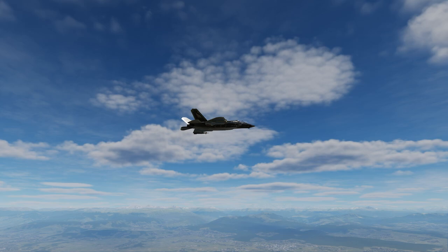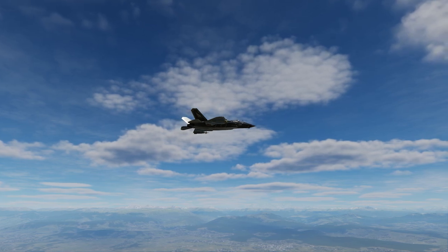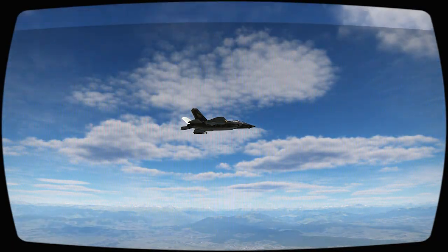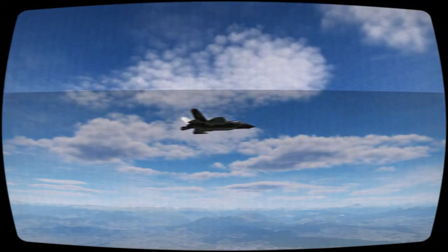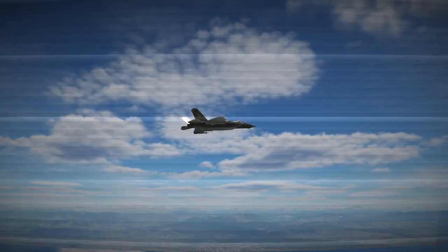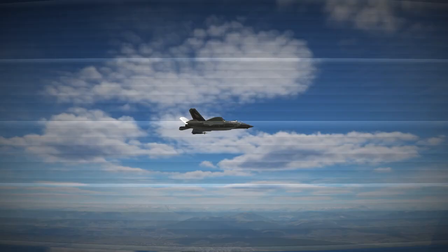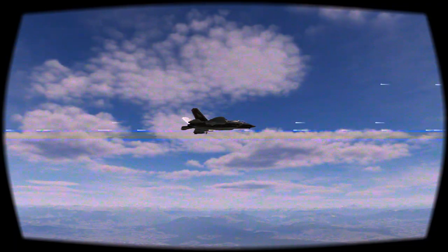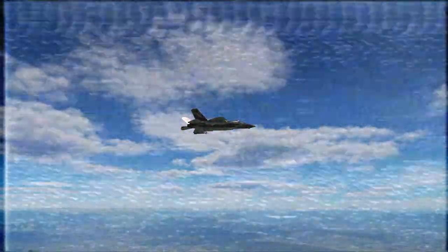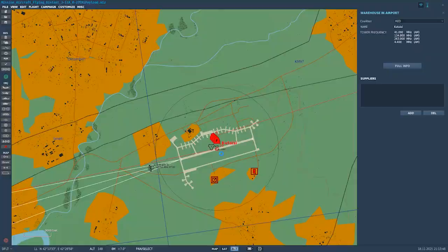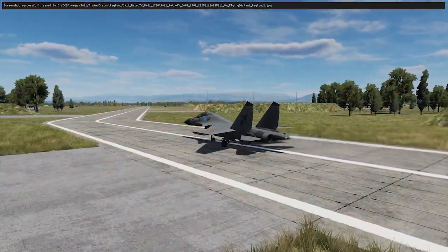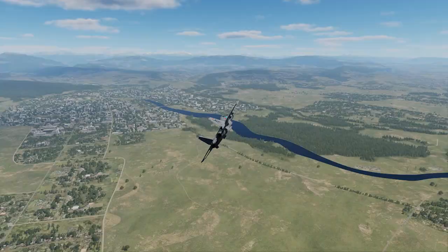Given that images in the computer are created without natural camera artifacts, we utilize tools such as Reshade to apply image filters on our captured images to help simulate real-world camera response and image degradation. These filters approximate different camera and image looks, including analog CRT and VHS looks, to also account for lens distortion. This variability strengthens our trained AI models, making them more resilient and capable of performing under a wide range of operational conditions. We have created custom missions to support different scenarios, including generic and more basic taxi, takeoff, and low-flight cruise type missions.